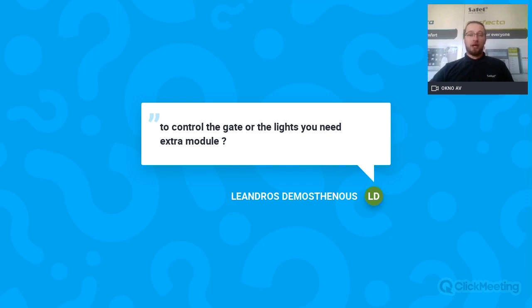But I always advise making a galvanic separation between the system and something like a garage controller or anything else, by using some kind of relay, even a cheap one, like a €1 or €0.5 relay, just to make a galvanic separation between the systems. But if it's 1 or 2 things that you want to control, like a gate, I think I will use the simple one.